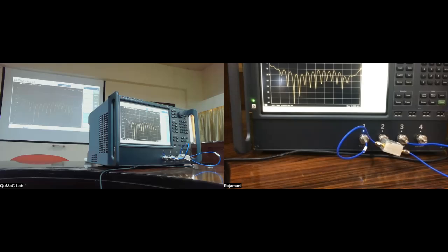So what's the use of this kind of a device if I'm using it in the opposite direction? Right? This direction is simple. The purpose of this device is to put power in and get 2 copies of the signal, 50% on each arm, plus whatever insertion losses. But in the reverse direction, if I send in power here, nothing goes here, 50% power comes here. So that's kind of a strange thing. It's not really useful in that sense.